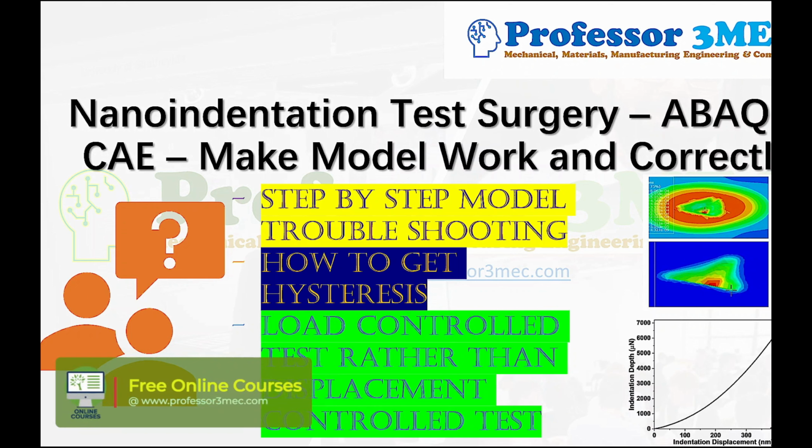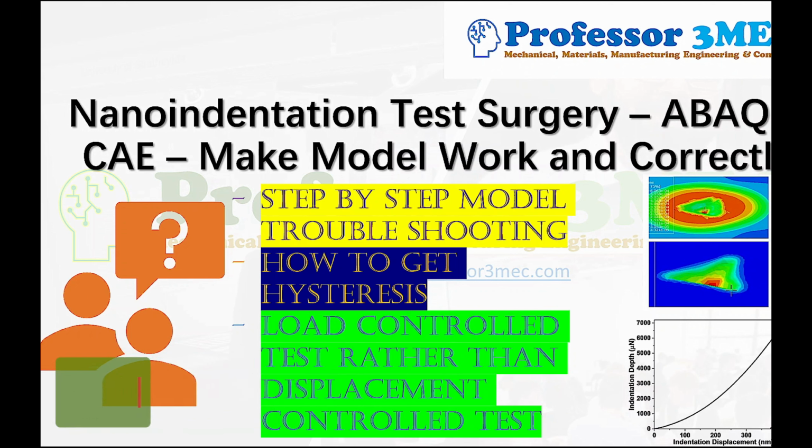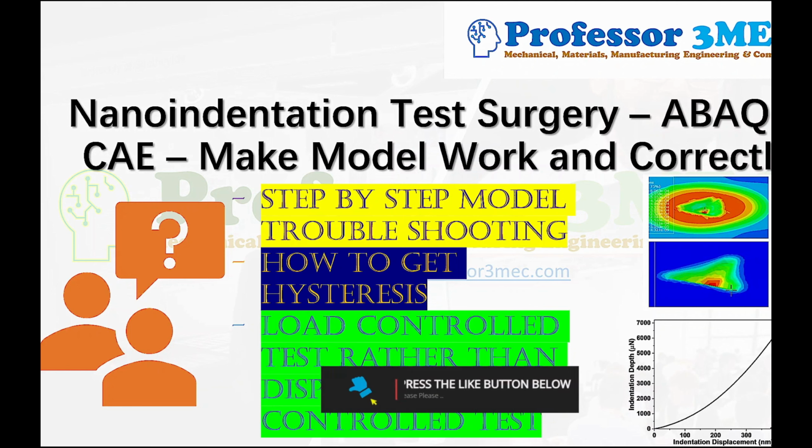Today I have come up with a surgery where I have received a model for an indentation test from a subscriber, and I will make this model work, and not only work but work correctly. What you will learn is step by step model troubleshooting, how to get a hysteresis, which you see on the right hand side here, and also if it's a load control test rather than a displacement control test, then how to change the loading and boundary condition.